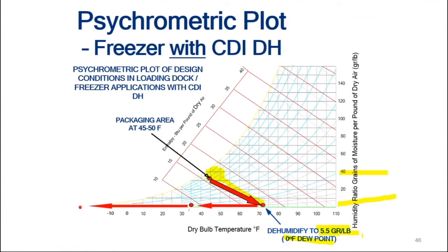So in those applications where we're talking about freezers, we're talking about desiccant becoming a 90% solution, 95% solution. You're going to ask Dr. Dry, how do you know it's a 95% solution? Well, if right now you're operating at this zone up here in this level of moisture, and with the desiccant we can get you to this zone. If we're down to, say, 5 grains, if I take 5 and I divide it back into, let's say for easy math, 50, that tells me that it's a 90% solution. So if before that freezer was seeing all 50 of those grains, now it's seeing 5 of those grains.